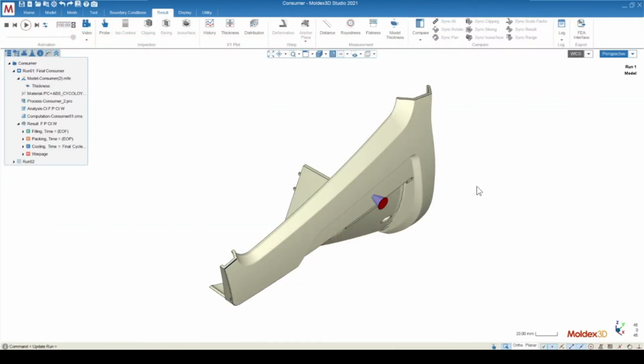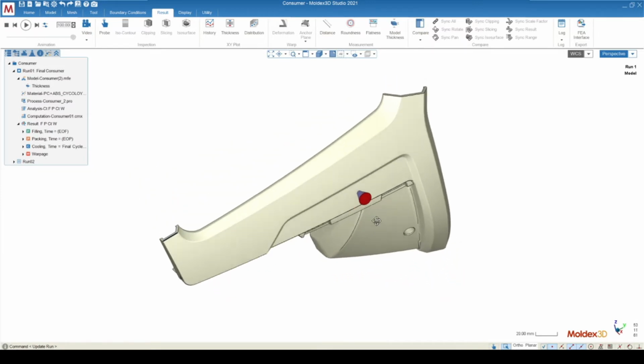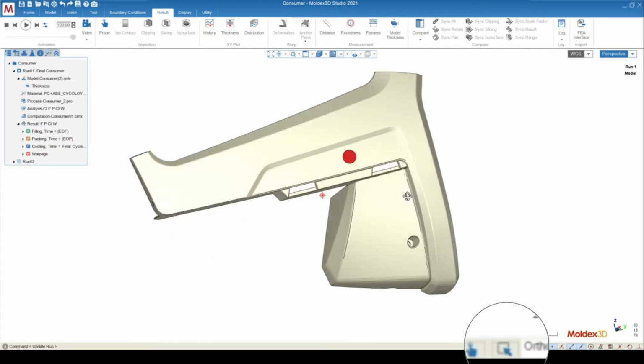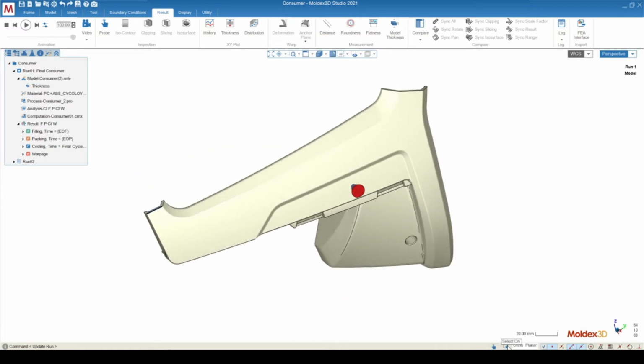In the UI or user interface, users can look forward to left-click dragging to be able to rotate. This can be especially useful when coming over from CAD softwares that utilize that sort of mouse interaction. By default, the right-click drag is still going to be rotate, but if you deselect this toggle down at the bottom right corner of the screen, that will enable you to left-click drag. This disables the selection function, so you'll want to toggle this on if you want to select an object.